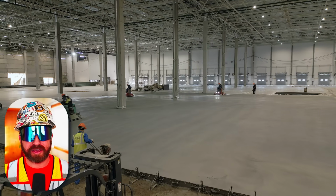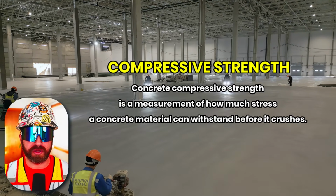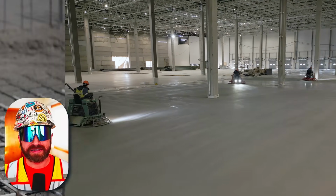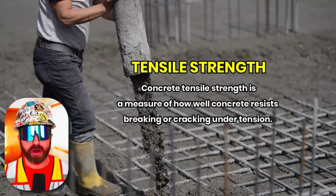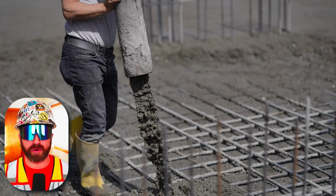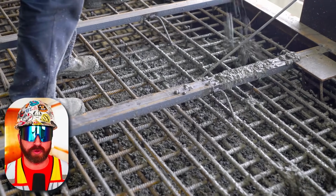Okay, so whether you're working on a residential or commercial construction project, you're likely going to have some sort of rebar, which is a structural element of your building footings, foundations, masonry walls, sidewalks, driveways, drive lanes, building slabs, or even precast concrete. Now, concrete provides high compressive strength, but is weak in tensile strength. Compressive strength refers to the material's ability to withstand forces that push down on it. Tensile strength refers to the ability to resist forces that would try to pull or stretch it apart. Rebar provides high tensile strength where concrete does not.